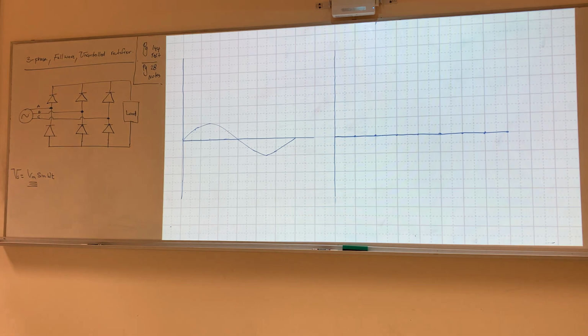This is my bridge right here, we call it bridge. And we have 6 diodes. So let's follow the phases, the currents. We will have, as I told you before, 3 phases. If this is A and this is B and this is C, the phase shift between phases is 120 degrees, and also between phase B and C is 120 degrees, and 120 degrees between C and A.